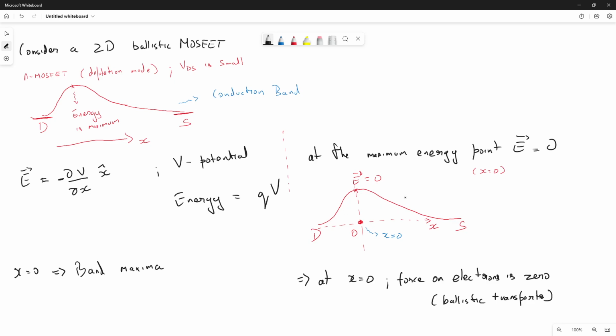There is going to be a band diagram of this kind, and by some means I will try to distort this band diagram in a particular direction. In field effect transistors, I do that by the application of an external electric field. In bipolar junction transistors, we inject minority carriers.